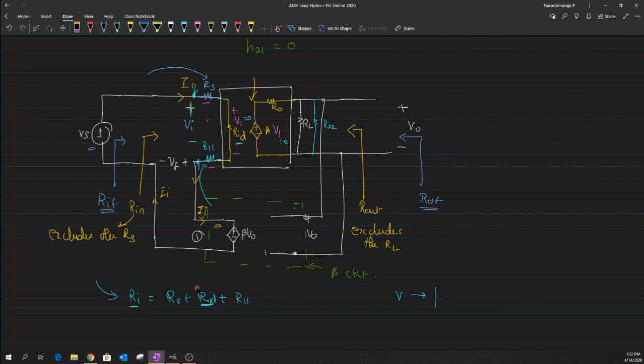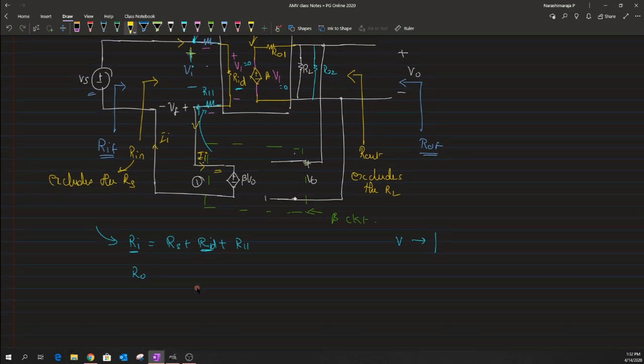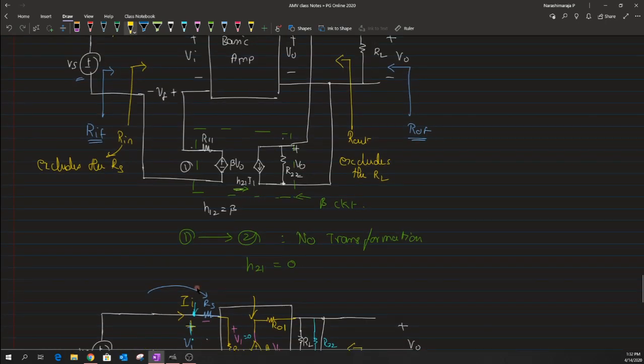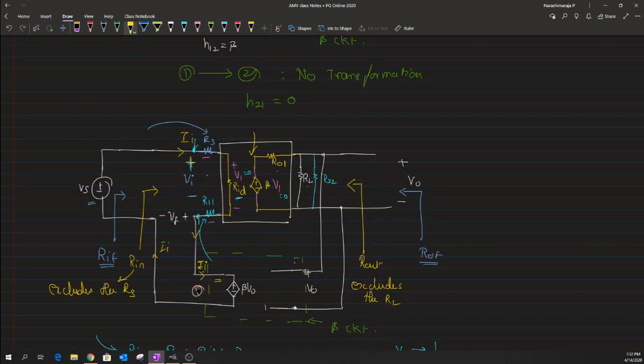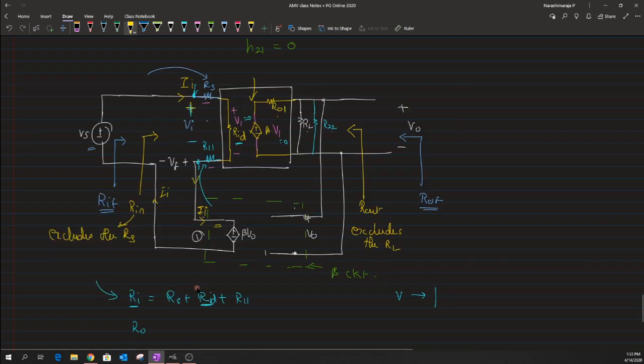So in that case, one could see that, again, I have to rewrite the actual resistance with something else. So let me write it as Rho1. Let me use this Rho1 as the internal output impedance of the basic amplifier, so that one could see that all these impedances of Rho1, RL, as well as R22, all these resistances appear in parallel, just because of the short circuit that we have made onto this.